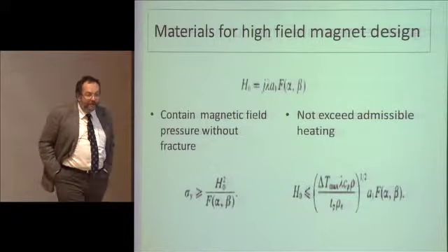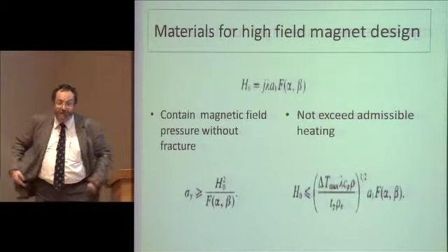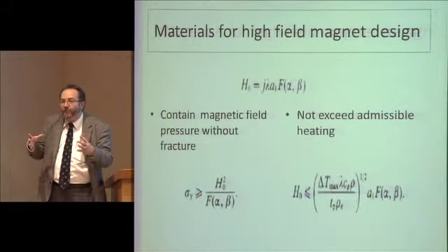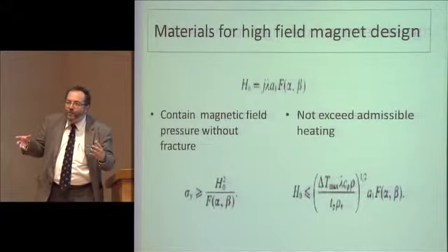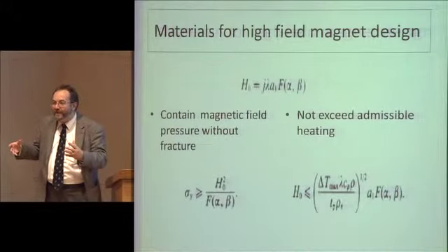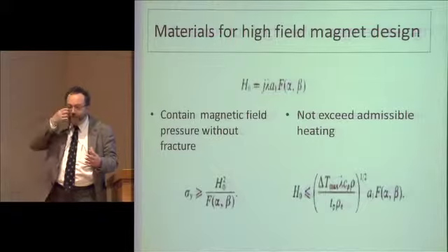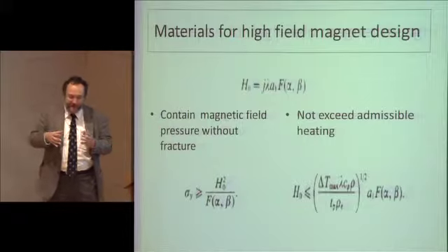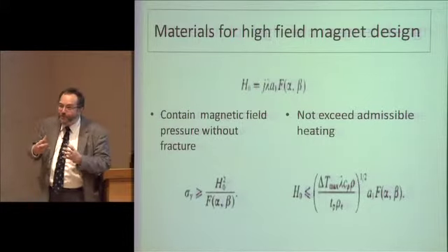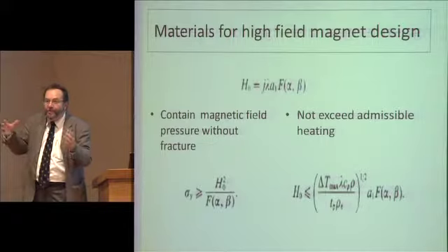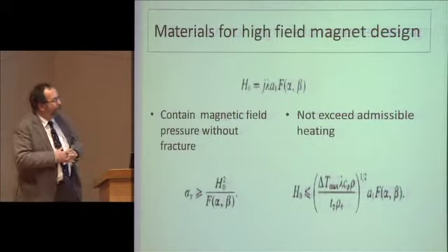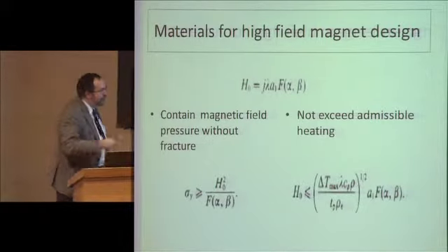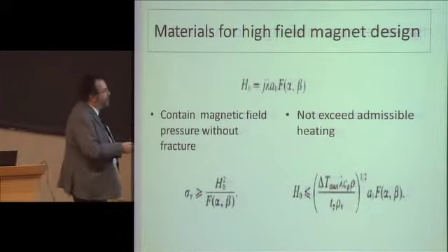If you go to a lab in Toulouse, they can show you a museum of horrors, which is all of the magnets that exploded, because when you have a magnetic field, you're creating huge energy, and per volume unit it's something that varies like the square of the magnetic field. And when you have 10, 15, 20 Tesla, confining it within the magnet comes with very, very high magnetic pressure. So one thing that you need to do is to contain this magnetic pressure.